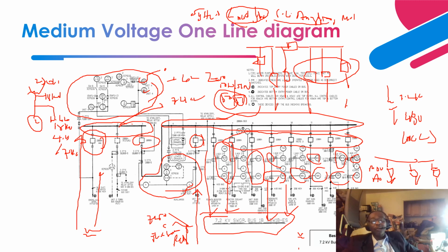Then you also perform short circuit analysis, right, to determine the withstand of the equipment based on its short circuit capability, right. That is how the bus ratings are determined, right. So the bus has a continuous current rating, a nominal voltage rating, then a short circuit capability, right. The short circuit capability is based on symmetrical rating and asymmetrical rating, right. So these are all determined based on system studies.